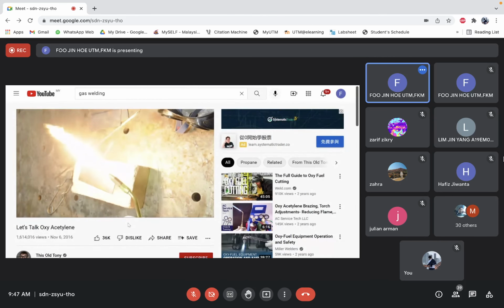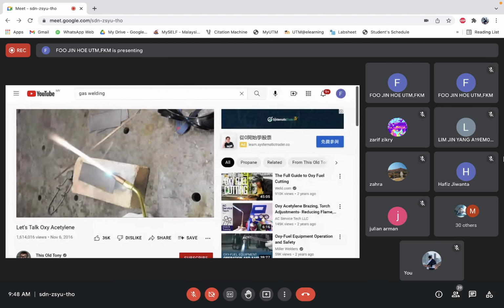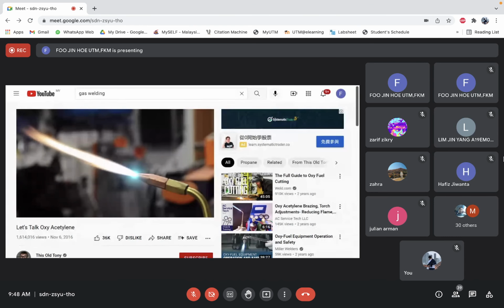And like before, slowly add the oxygen or reduce the acetylene to get the balance right, to get us to a neutral flame. I'd hope this would go without saying, but I'm going to say it. The flame is very hot. If you've never used an oxy-acetylene torch before, you likely have no real reference for just how hot this thing is. You don't have to take my word for it. Let's see what the thermal camera says.